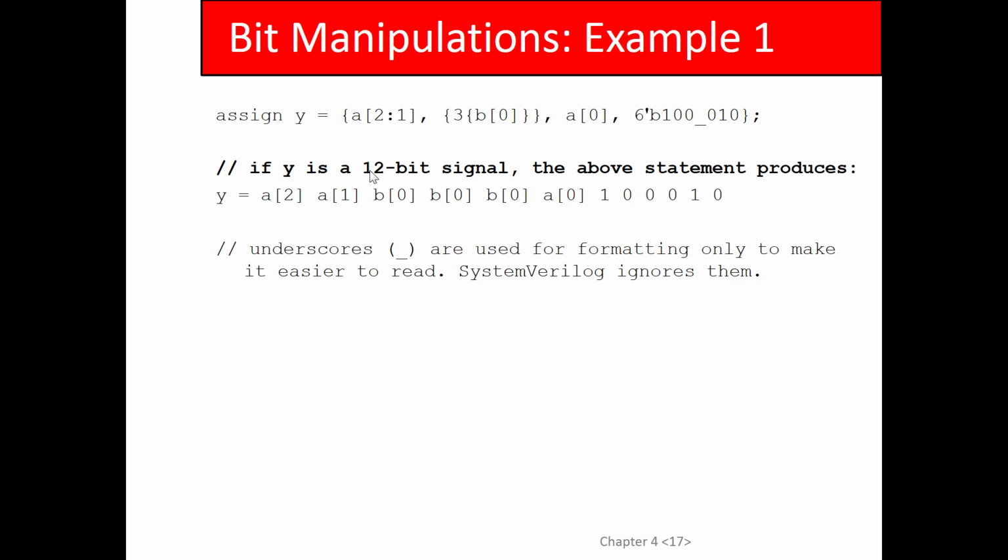What do you mean when you say it takes out the bits from A? Oh yeah. So let me give you an example. I don't know how big A is, I'm just going to assume it's 4 bits. So let's say I declared A like this: logic [3:0] a. And then let's say I assigned A equals 4'b0110. Then I take A and I do what they did there, just 2:1.